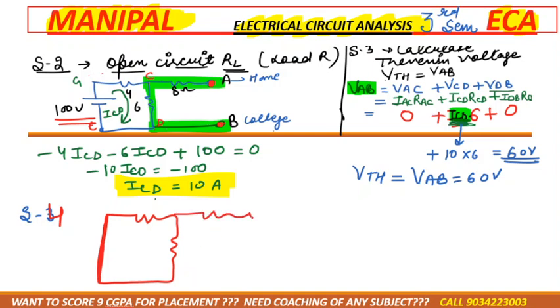And in this case the rest of the diagram would be the same, 4, 6, 8. Now just imagine you are standing at A, you need to move towards B. Just imagine that 4 ohm, 6 ohm and 8 ohm are your friends. If two of your friends are on the same path, that means they are in series, and if two of your friends are on different paths, that means they are in parallel. Now you will start from the friend who is very far away from you, 4 ohm.